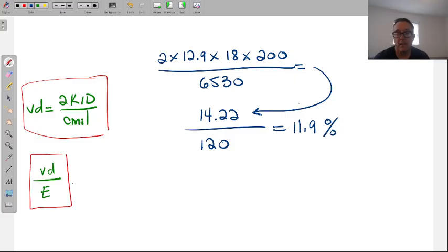Percent-wise. That's why, as you get more experience, sometimes you just look at the voltage number and go, nah. Like 106 is a number that I would not be comfortable with on a circuit that should be expecting 120 when they plug in. Remember what that does to the amperage. Once we drop to 106 volts, that's going to increase our amps. And in a 120 volt world, you might be dealing with a 15 amp breaker. You might be dealing with a small fuse.